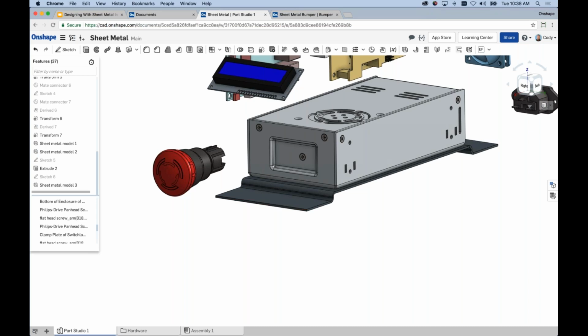Question, back cutting is a machining process in the sheet metal part where a saw cut is made on the back surface. You bend at that cut so that your bend radius is tight and does not follow for sharp corners. I don't think we're going to have a specific operation for back cutting. I'm sure you could create the shape using our normal commands, but there's no back cut specific operation or feature in Onshape.